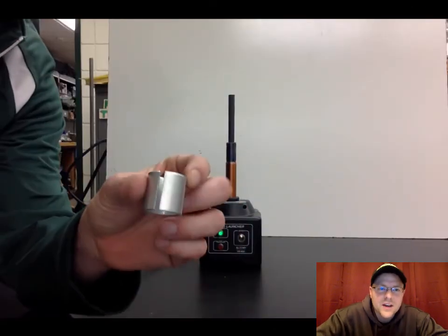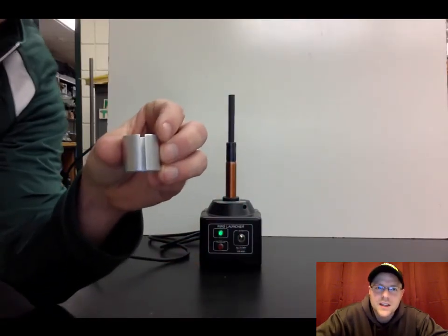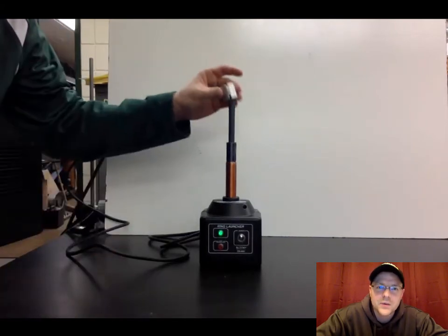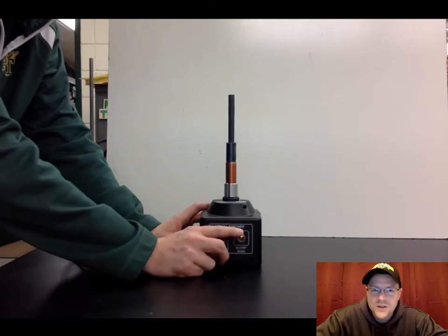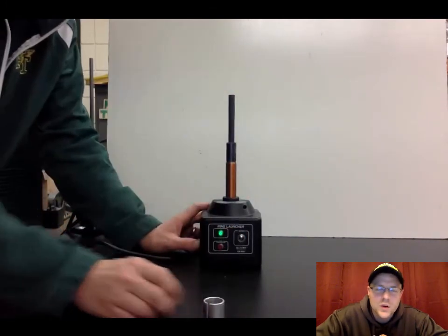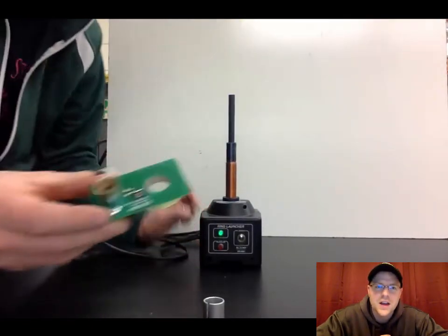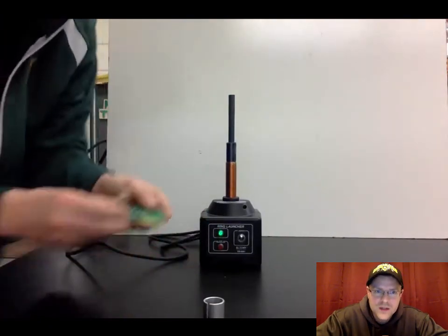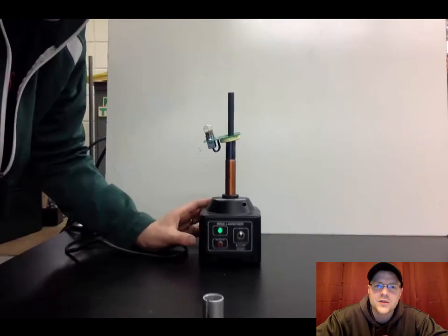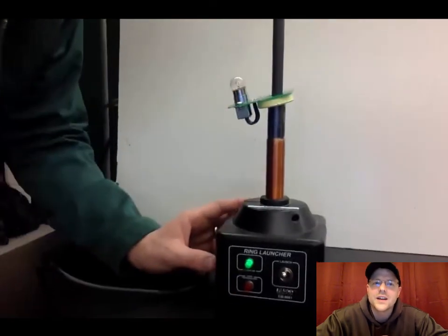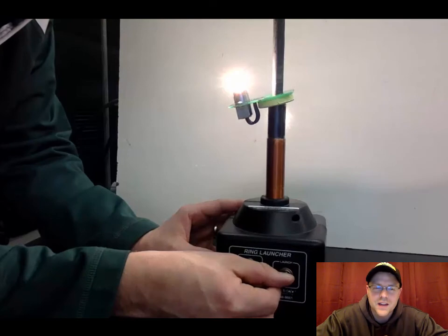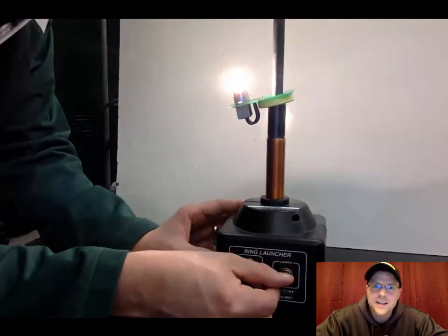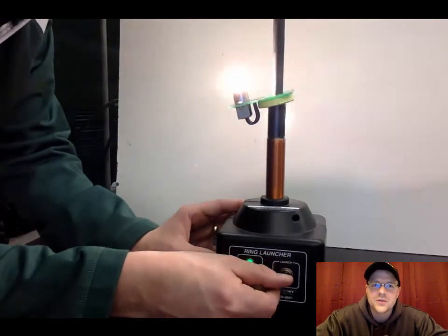Now this last one I have, you can see there's actually a little cut in the ring. So if there's a cut in the ring, when I push the button, nothing happens. And the reason nothing happens is because there's a cut, so we're getting no eddy currents and no induced currents to flow around. This last one is a light bulb that has a coil of wire on it, and when I put that coil of wire across this solenoid with the AC current and turn it on, it creates electricity. And that little light bulb is not attached to anything except has a changing magnetic field going through it.